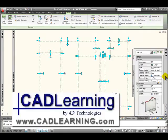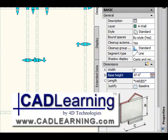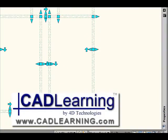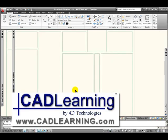I'm going to make sure that my walls are set to baseline. I'm going to change them to 5 inches, and I'm going to change the height to 12 feet. Press Escape. And we now have our walls drawn. I'll go ahead and place some doors in here.